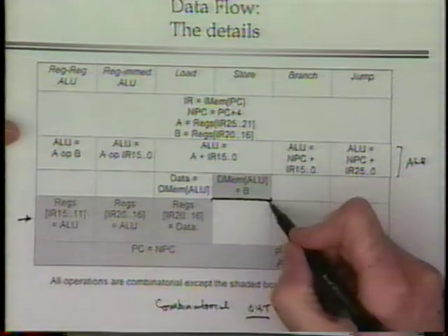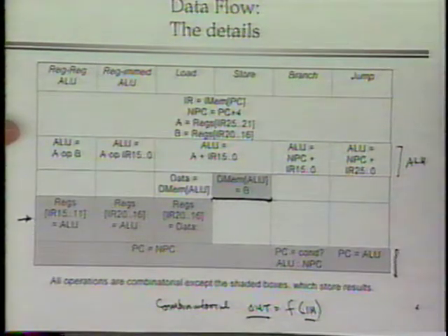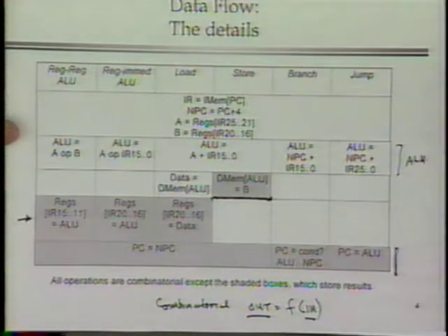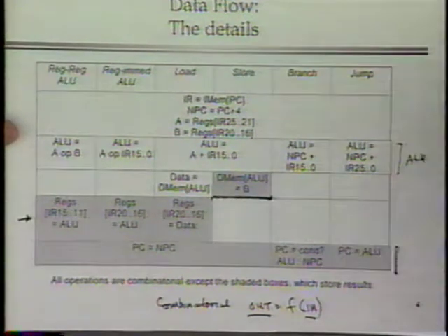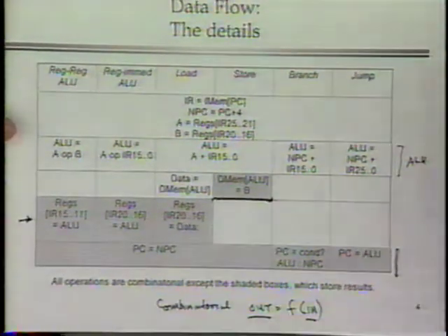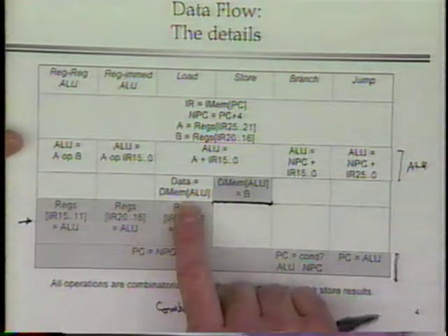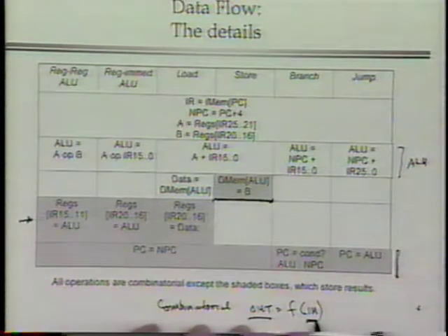For memory writes, you can't quite be that simplistic, because there's got to be a signal that says the data has been stable for long enough, the address has been stable for long enough, now's the time to remember that information. Yeah? What I was saying is the address could be invalid. Sure. In fact, for all of this combinational logic, as soon as the input changes, the output may be invalid for a while.